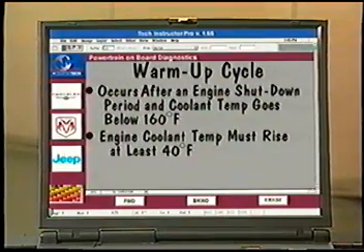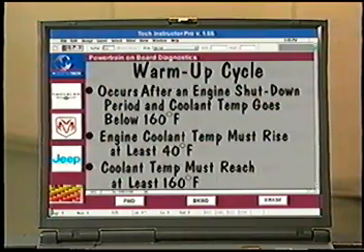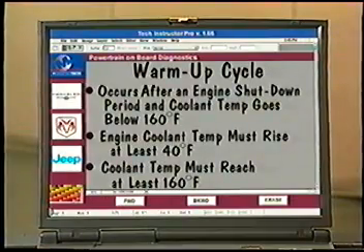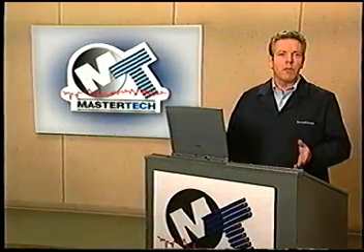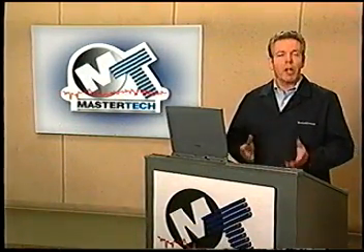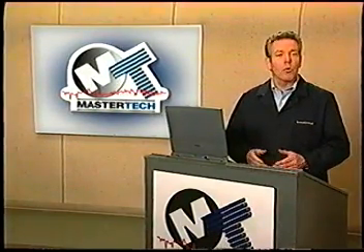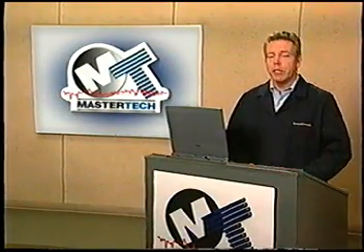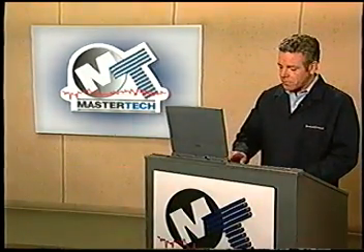In order for a warm-up cycle to be complete, during vehicle operation, the engine coolant temperature must rise at least 40 degrees Fahrenheit, and the coolant temperature must reach at least 160 degrees Fahrenheit without any further faults. For example, suppose the vehicle's engine coolant temperature is 159 degrees Fahrenheit at startup. The warm-up cycle will complete when temperatures reach 199 degrees Fahrenheit without any further faults.